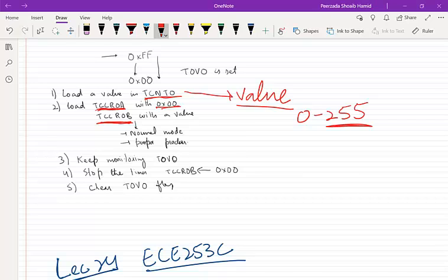Timer control register B will give us the mode, whether we want to use timers as timers or as counters or other modes, and it will also determine the prescaler, whether we want to run the timer at a frequency equal to the frequency of the crystal attached to the microcontroller or at some other frequency. That is the prescaler. If we don't want any prescaler and we want to run timer 0 in normal mode, we will load TCCR0B with